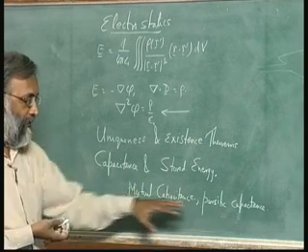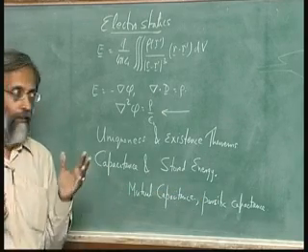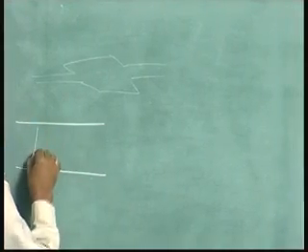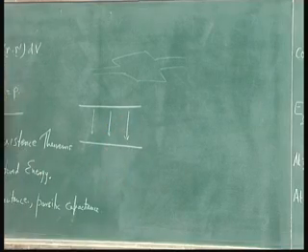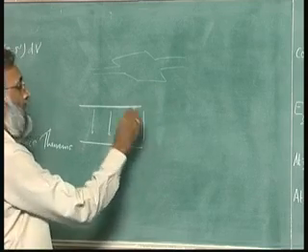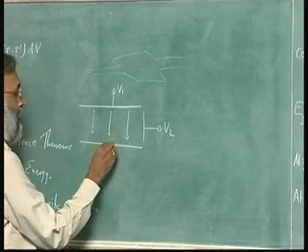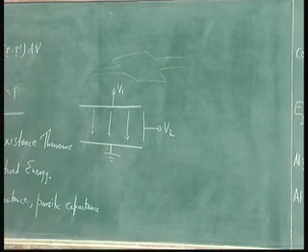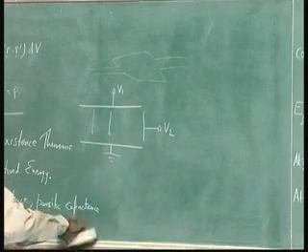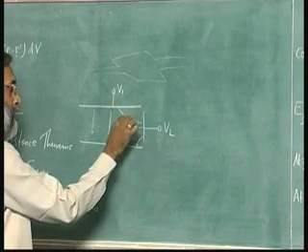So parasitic capacitance and mutual capacitance come from the possibility that electric flux lines don't always go from one plate to another. It's possible that you may have multiple plates. Maybe I have a plate held at voltage V1, another plate held at voltage V2, and the third plate is grounded. In that case, instead of all the flux lines going between V1 and ground, I will have some flux lines going from V2 and ground, and some flux lines perhaps going from V1 and V2.